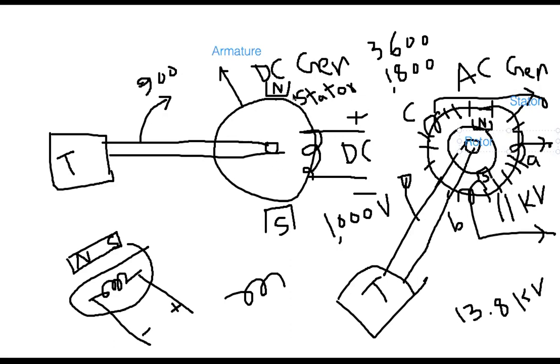In case of DC generator, because it is only one set of coils and they produce less voltage, it could be maximum 1 kV. That's why typically this body is rotated and the field remains static. You could do the opposite thing as well. Of course, voltage will build up, but all over the world, common practice is to rotate this body and fix the magnetic field.